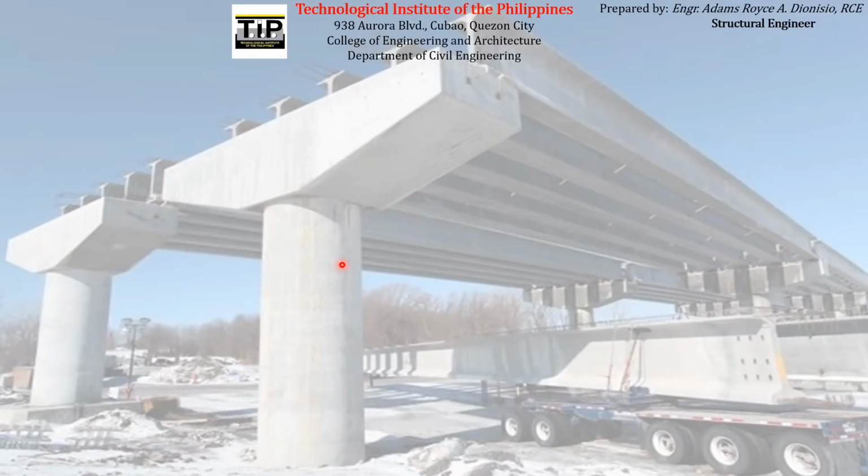So now we are already familiar with the different causes of the occurrence of prestress loss that the code wants us to consider when computing the magnitude of the effective prestressing force. So now, let us discuss all of those causes individually. Let us start with the elastic shortening of concrete, which is usually designated as ES.